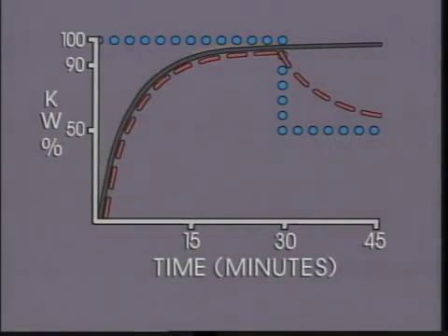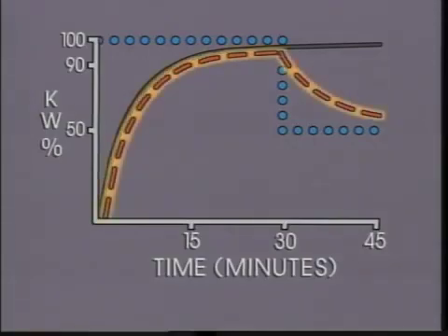It's also important to note that demand registration for a thermal meter is continuous. Notice by the dashed line indicating the movement of the pusher arm that the pusher arm does not reset at the end of regular time intervals. Instead, it moves up or down scale in response to temperature changes resulting from load changes.